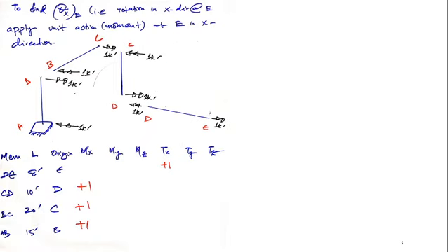Next I have to calculate the moment table, and you should know that my origin is E for this section, and this is actually X. So this is acting counterclockwise, so here it would be balanced with pure torsion in clockwise direction, +1. That's why it's +1 here. In member CD, my origin is D. I have to find all moments here, and you should know one kip foot is acting counterclockwise. It would be balanced with equal and opposite one kip foot, and this is clockwise. That's why it's +1 here.